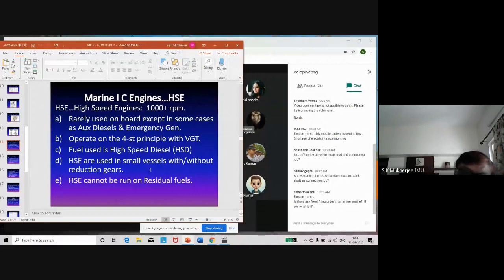These propellers are made of stainless steel, and their pitch, their diameter, their specifications are matched to allow for high-speed rotation. So in high-speed engines, in small patrol boats, speed boats, they are directly driven from the engine. No reduction gears required. And if you must know what is the fastest speed of a vessel moving on water, it is something like 105 miles per hour.